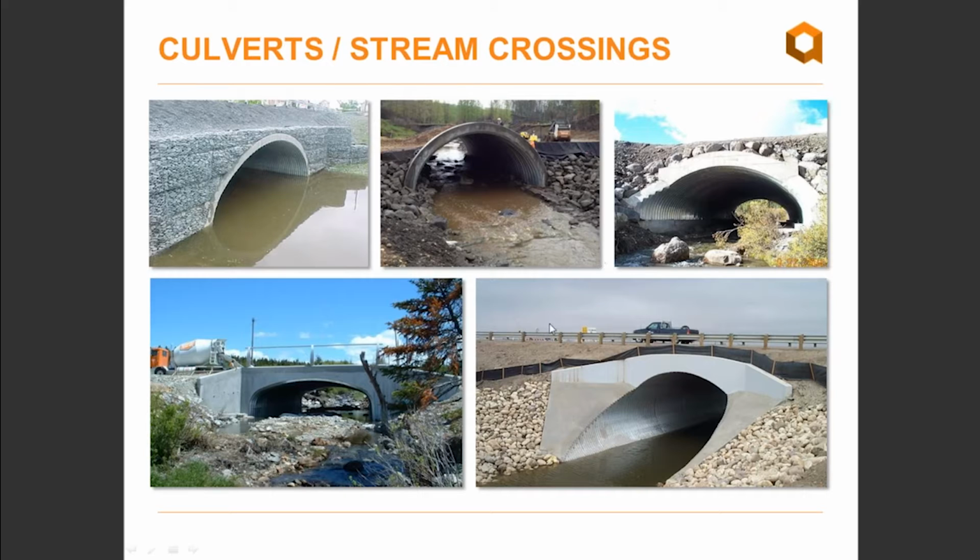So didn't really talk about gabions, but that's another option that's available. Just woven geosynthetics or GRS walls as well, something we've gotten into, and then beveled end treatments just with a cast in place collar reinforcement at the end of the structure is very common as well.